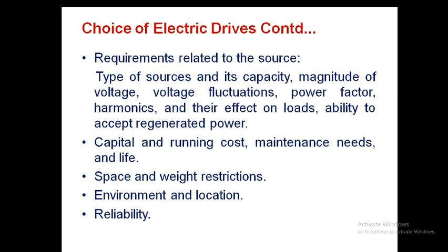All these factors matter, whether the drive needs to regenerate some power, or it can simply waste that power by connecting some rheostat. Or the type of sources, like voltage levels, whether it is low power or high power requirements. Based on that, we need to choose the electric drive.